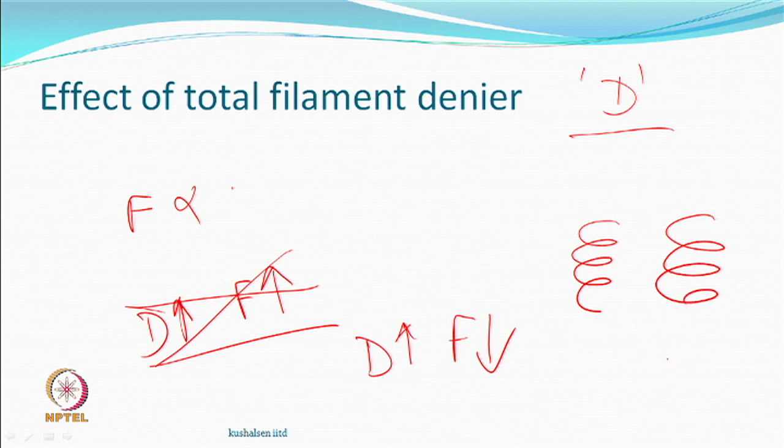So, if you have two situations where the diameter is this of the helix versus this, in your own opinion, which one will be offering more resistance if the individual denier of the filament is the same? The one with the larger helix or smaller helix? The smaller helix therefore is going to offer more resistance.